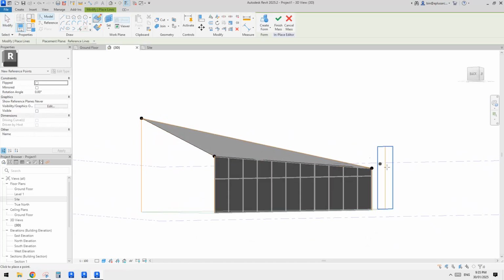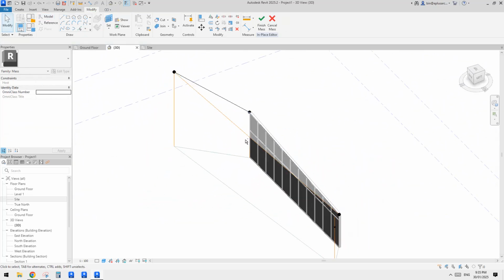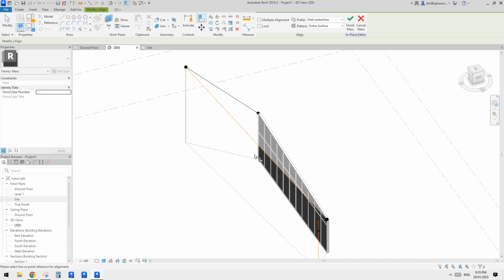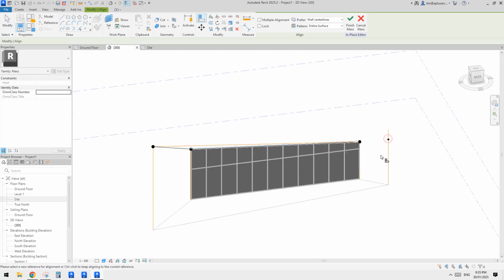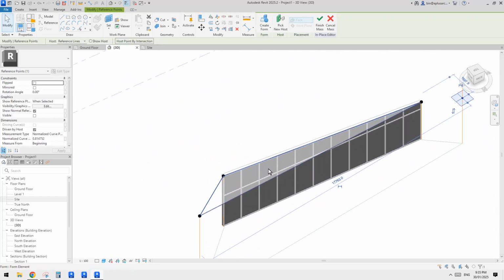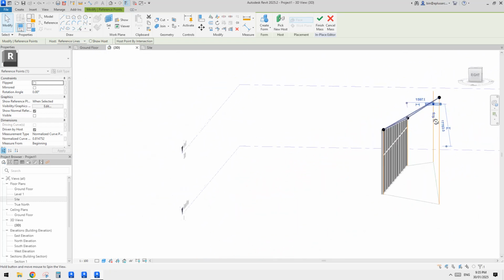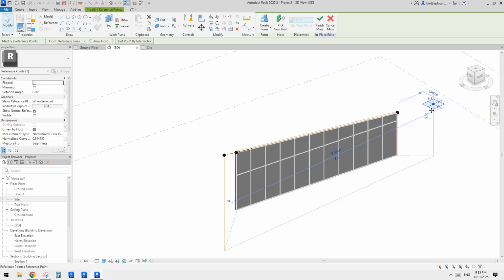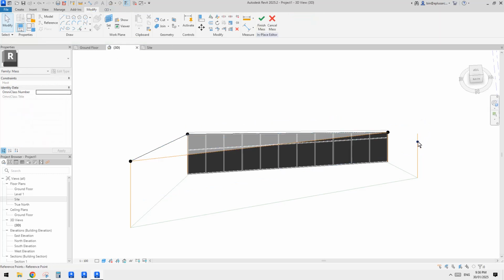And then we can just do a point, draw on face, place onto this reference line, and then we can option there. You can have option, you can align and pick this surface, and then pick this point. So this will make sure this point is on this plane. So if you extend this plane, it will go through this point. Or you can also do, I'm not sure, hold point. Yeah, I think you should be able to do this. So let me show you.